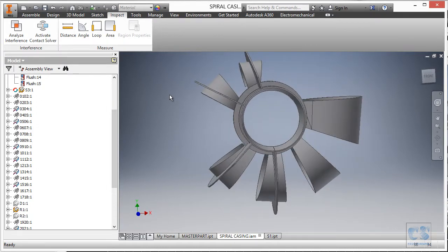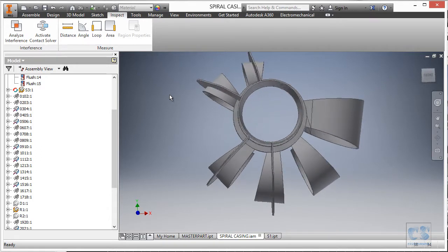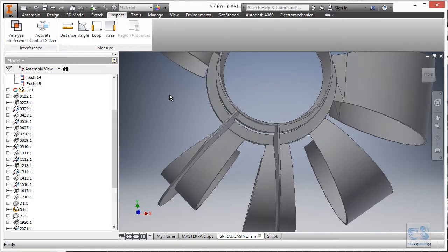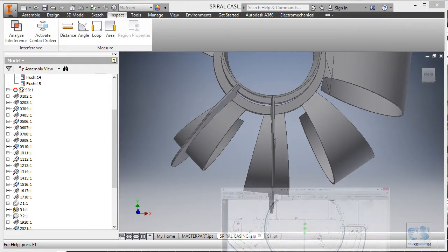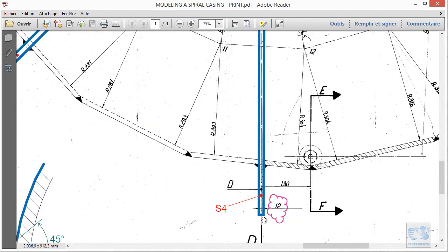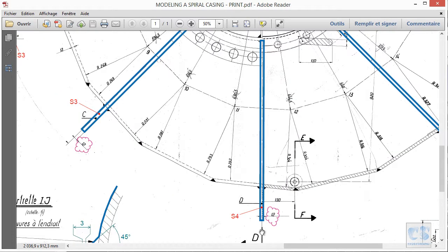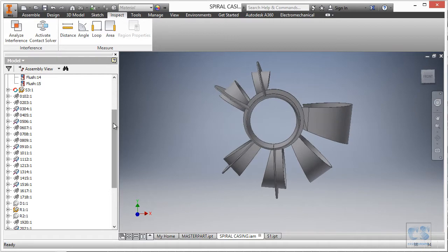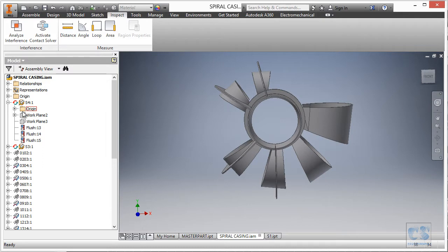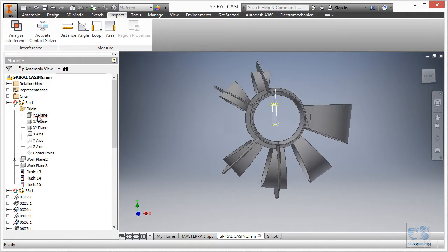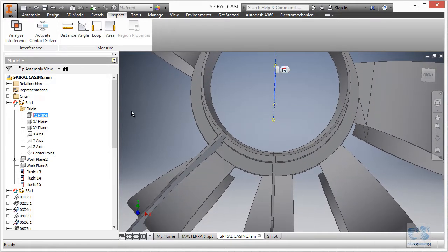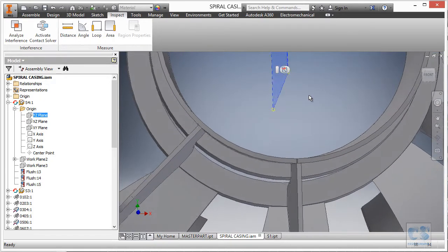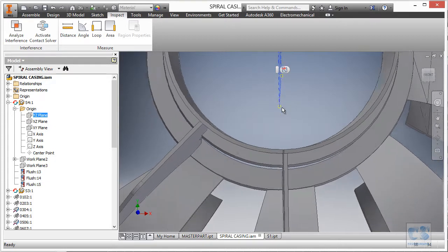And let's move to number 5. But before we do so, I just remembered that we have an additional operation, a special operation for this component, because as you can see, the midplane of this stiffener should be coincident to the ZY plane, and now it might not be the case. So we have this YZ plane and it's not the case. So we are going to have to make some additional change before we move to the next component.